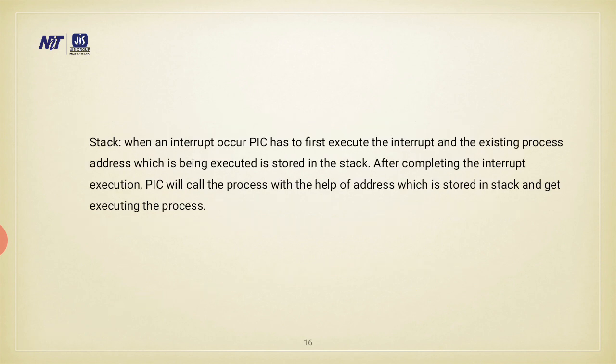Now, the stack. When an interrupt occurs, PIC has to first execute the interrupt, and the address of the process which is being executed is stored in the stack. After completing the interrupt execution, PIC will call the process with the help of the address which is stored in the stack and get the process executed.